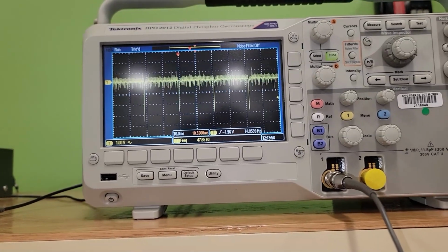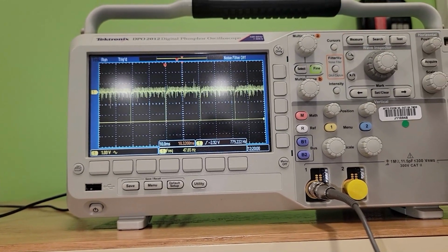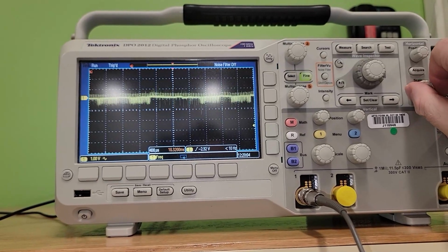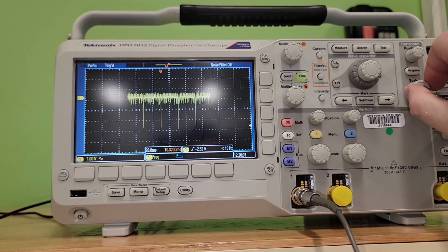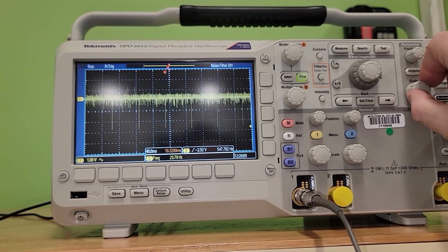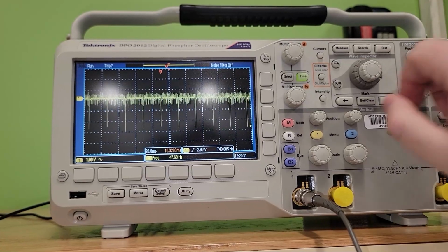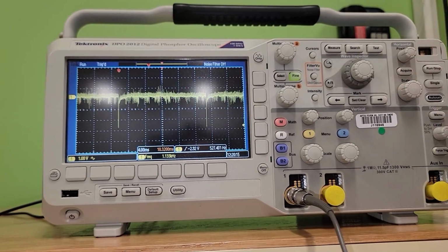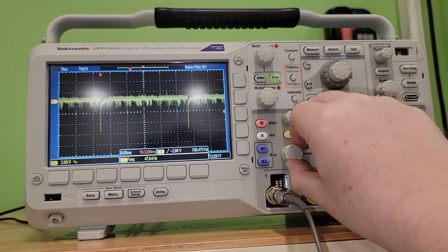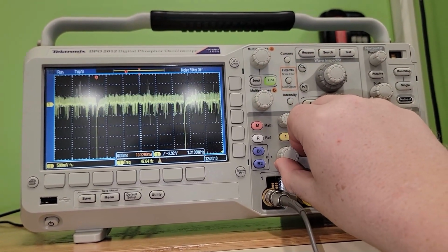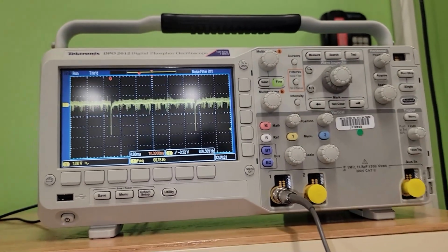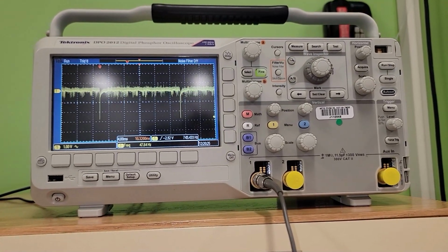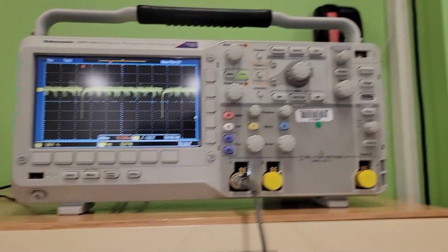48 hertz signal. Okay, trigger where it's best for you, but you can see that as I spin it out, you can get more on the screen or less depending on how I span. I'm more interested in those peaks, but I know when I'm seeing this that I am looking at my vertical sync signal. So we have RGB and we have horizontal and vertical sync.